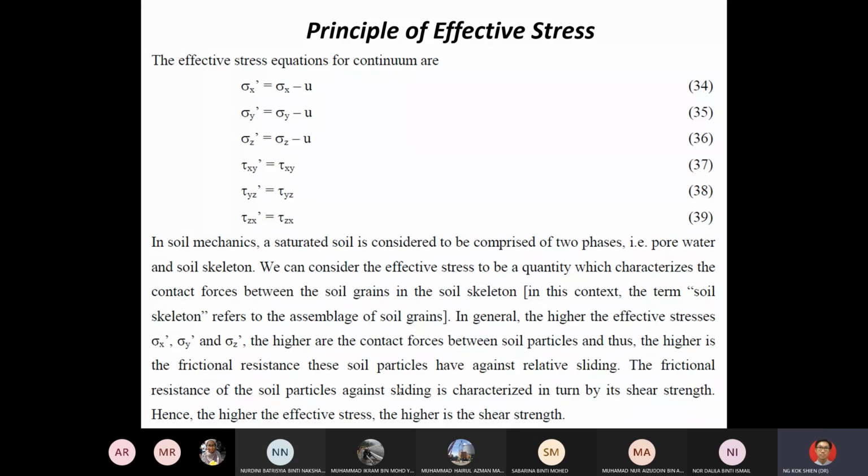not different kind of soil, the same kind of soil, same type of soil. Let's say it is a soft soil. So the soft soil on top or near to the surface normally has a lower shear strength compared to the deeper soil layer. I mean deeper depth. When the depth goes deeper, the shear strength increases. Okay? This one you need to remember.